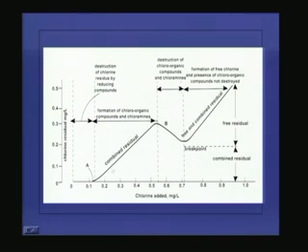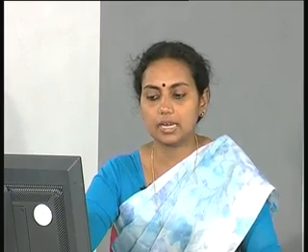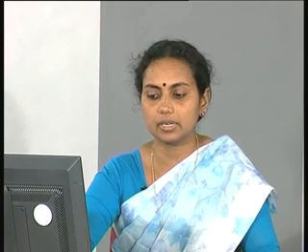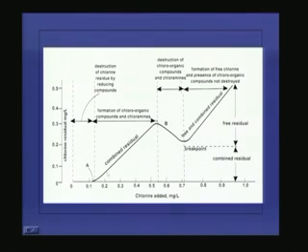So this is the typical curve for water having ammonia. If you have only distilled water and you add chlorine, the curve will be a line at a 45-degree angle, because whatever you add will be available as residual chlorine. But if you have a solution containing glucose or something like that, initially some chlorine will be utilized for the destruction of the organic matter, then again it will rise at an angle of 45 degrees. You will not get this type of curve. This is typical of the presence of ammonia.